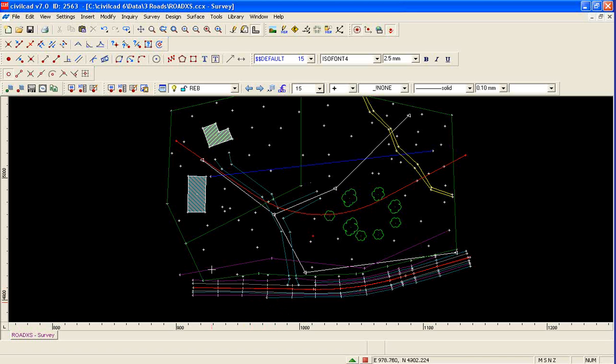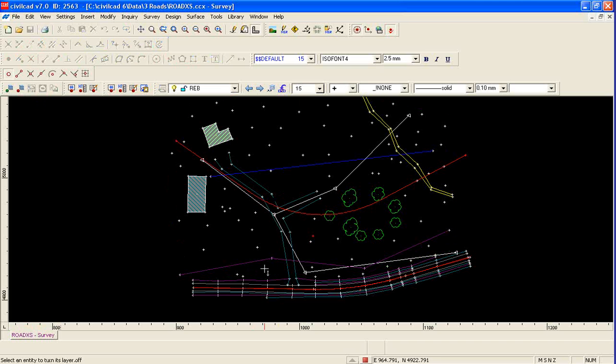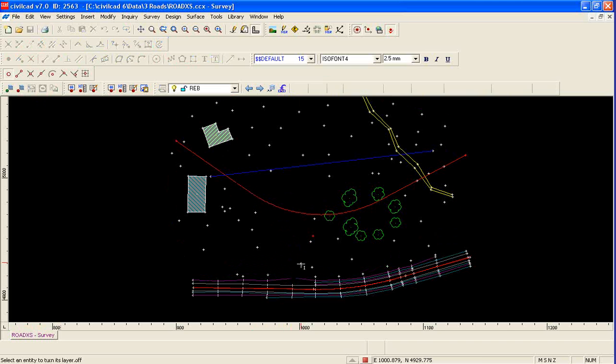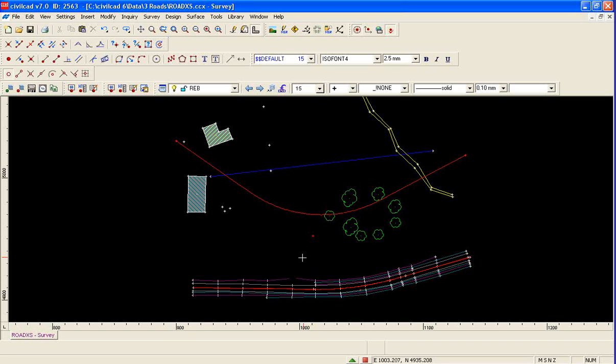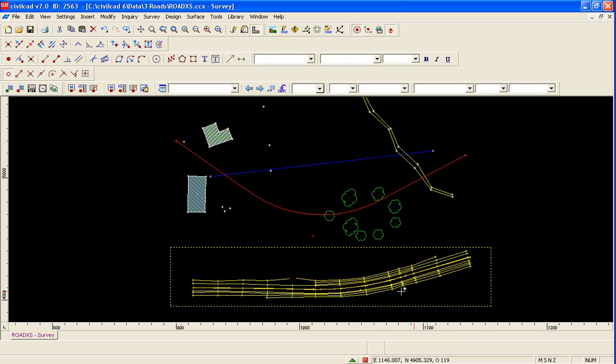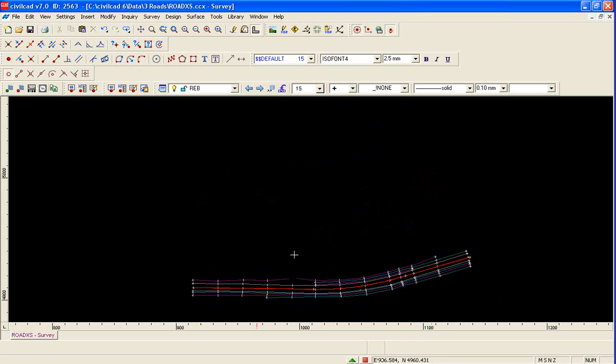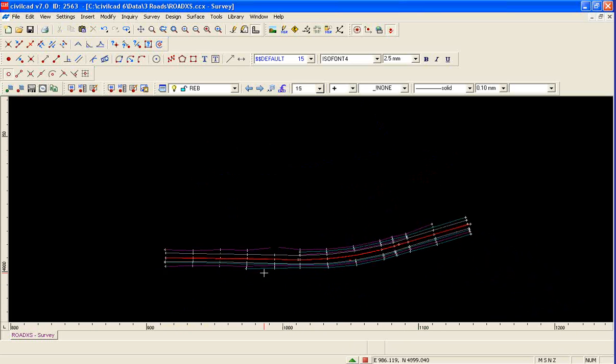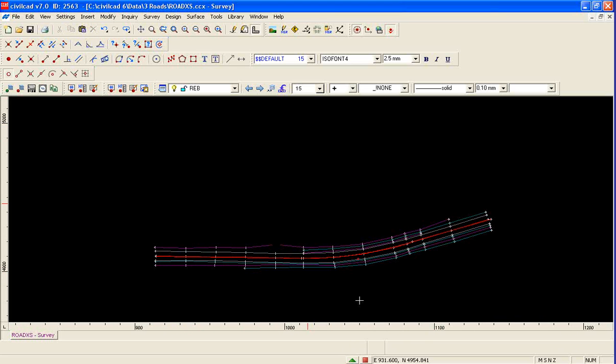called road. First thing to do is to isolate these layers using tools we learnt in lesson 1. So we can just turn off layers in the surrounding area, turn off the natural surface, and then if we just escape out of that option and drag a box to encompass all of the road layers and then just say isolate layers. Okay, so now we've got the layers on that we want to contain in our group.